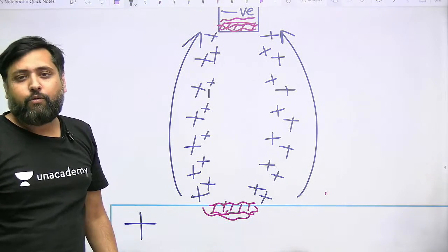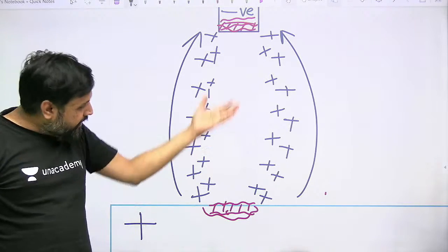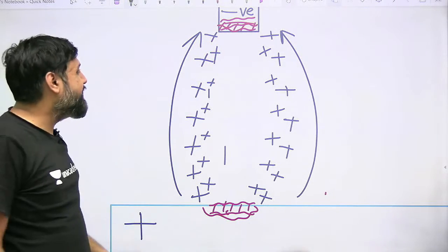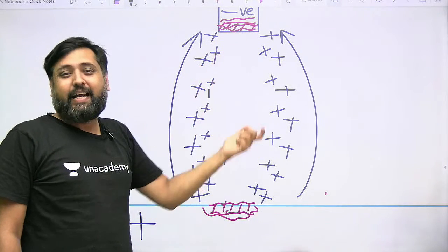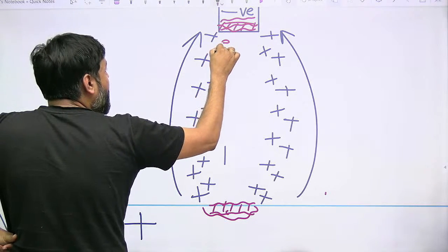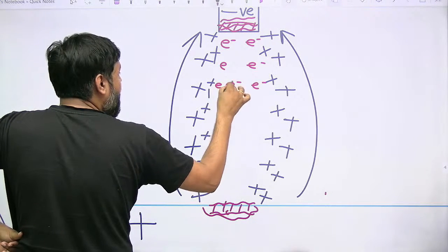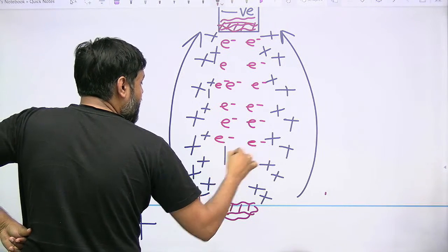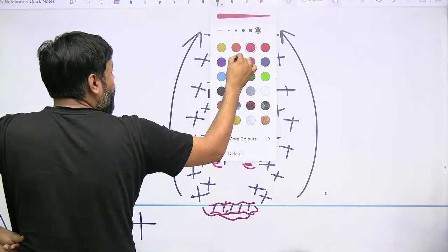The electrons emit out. At first, what happens because of this ionization? The resistance in this gap decreases a lot. When the resistance decreases, current can easily establish. You all know electrons can easily emit and travel through this ionized gap. So what happens now? From the negative side, the electrons come out, and these electrons now travel towards the workpiece side.